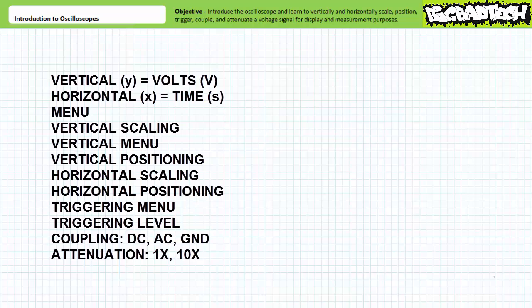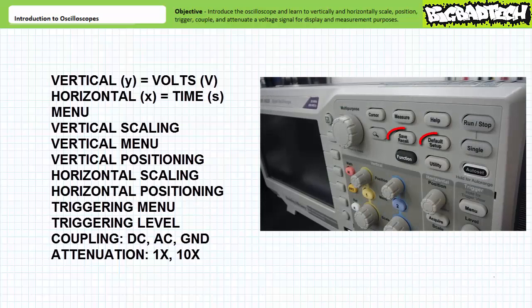Your job is to be capable of setting the oscilloscope up so it snaps out of it and flies straight. This is often a task of simply walking through this list and figuring out which aspect, vertical, horizontal, positioning, triggering, coupling, or attenuation of the waveform under inspection is distorted and rectifying it. Hopelessly tangled scenarios can also be remedied by restoring an oscilloscope to the default or some pre-established standard setup, and maybe lab standard operating procedures to begin and end each lab with a given condition.